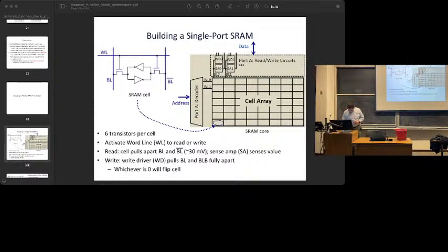So that's what these circuits are. There's one sense amp that's basically a differential amplifier. That's what a sense amp is. So there's a sense amp up here, and it's got these 2 bit lines going in as its inputs. One positive, one negative, and it just detects which one is higher. Okay, and if it detects that this side is higher, then it reads a 1. If it detects that this side is higher, then it reads a 0. Does that make sense?